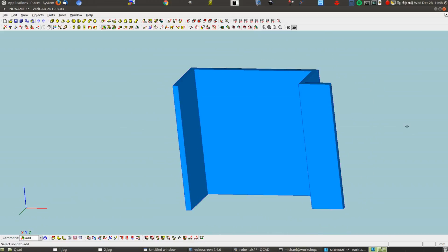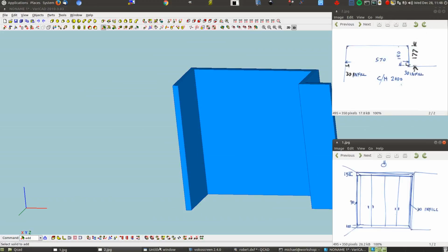What have we got reference to? Well, we can put the kick in place, and we can put the bulkhead in place, because we can refer to this wall to give us those placements. Okay, now what are our details? We have a 150mm bulkhead, a 100mm kick, and it basically goes from one wall to the other.